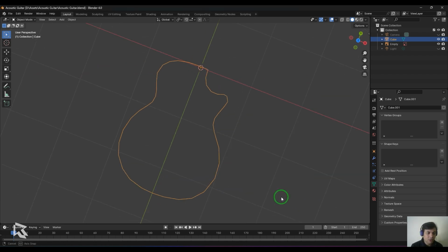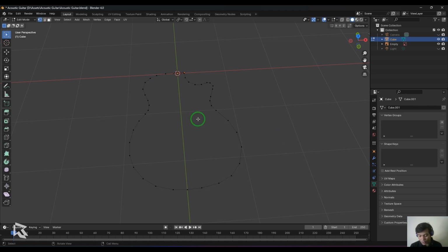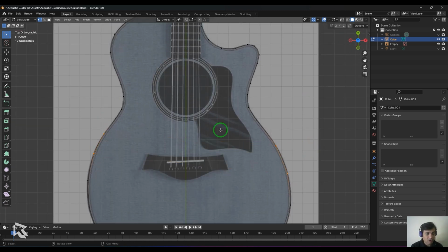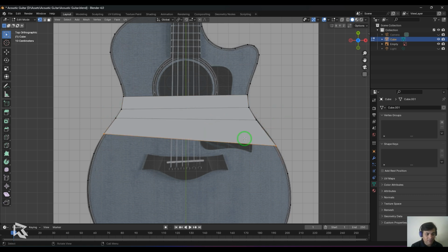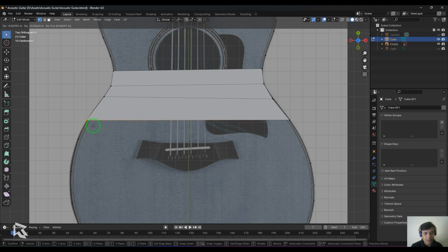I've built this as you have seen. So I'm going to select the model and press Tab, and then go to the top view and select a few of the vertices, and then press F, which will fill the points here. The biggest thing here is that these lines should be pretty much straight. So select these lower corner two vertices and press F, and it keeps moving like that. Once that is done, you should be able to place those points evenly on both sides. You should try to equalize those lines on both sides.